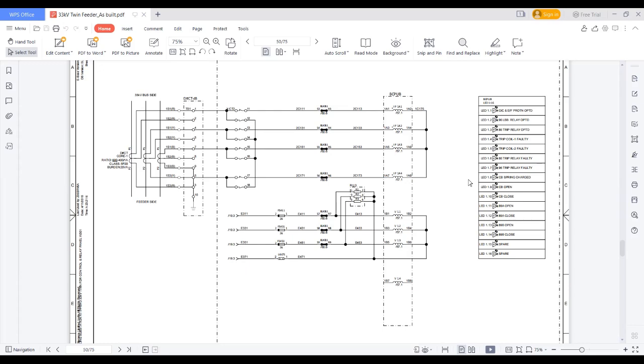So mainly, again, I just want to repeat: the AC circuit, DC circuit, PT circuit, current transformer CT circuits, and indication circuits, and master trip relay, LBB trip circuits, breaker closing and tripping circuits, breaker pre and post close supervisions, and isolator control and indication parts. So these are the things we can see in any scheme drawing. These are the common things. And I already told you how to review.